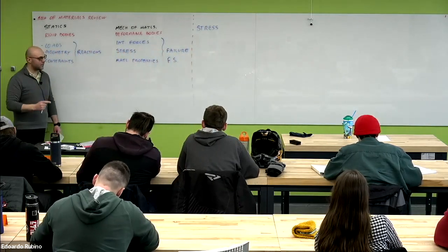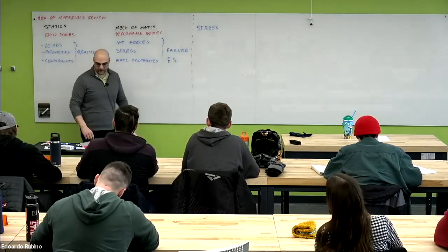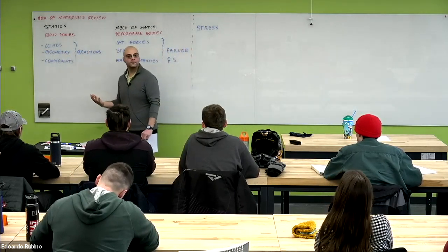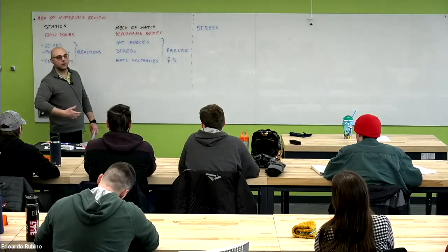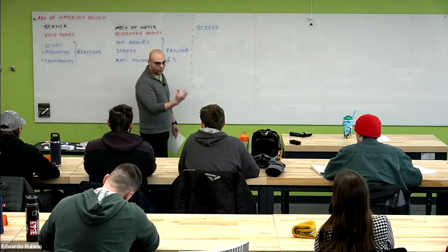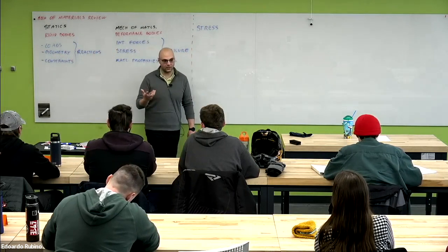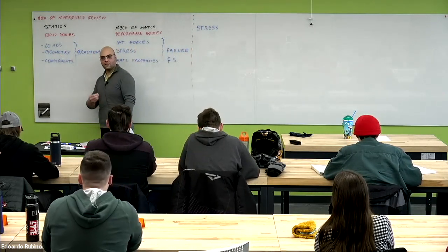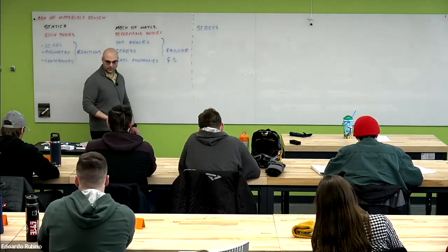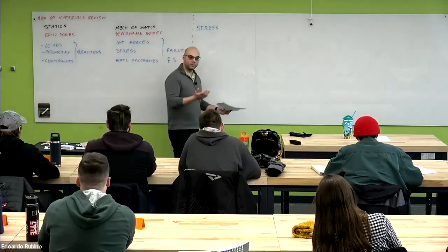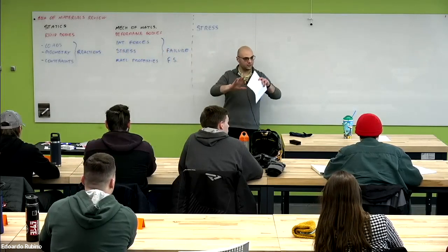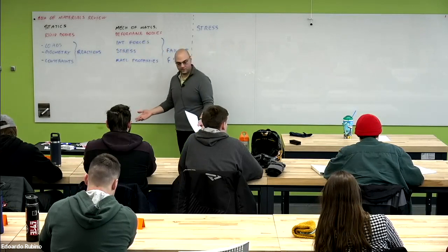Actually, even before that, we should start by thinking of the definition of stress. How do we define stress? Force per area. In order to determine the stress, we have to look at the amount of force that we have on a certain area. We divide that force by the area, and then we obtain the stress. It's the same concept as pressure, because pressure is also some force applied on a certain surface. So the units are even the same.